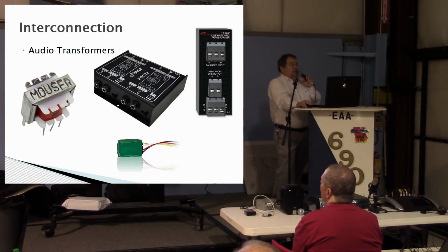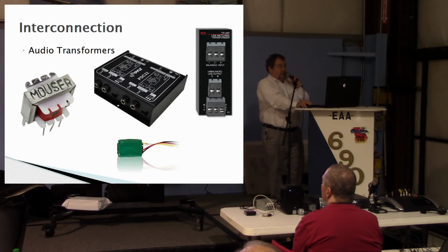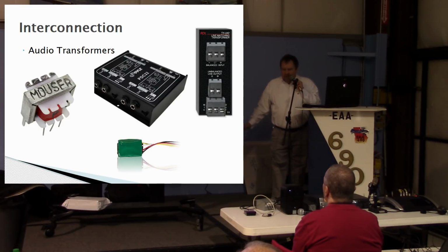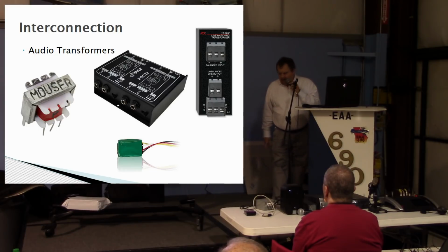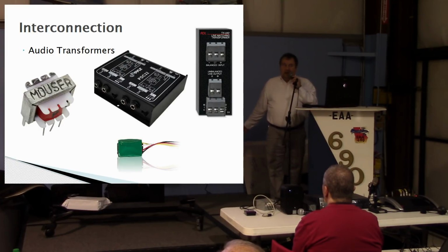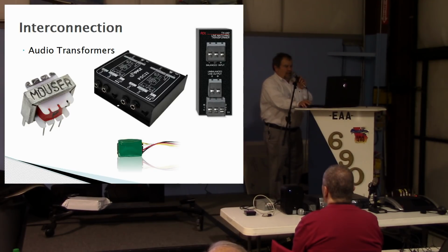You can buy a little box like this. This is called a direct box. This is used by the recording industry. You'll see them on stage with varying equipment. This is particularly important when you've got the mixing boards in the back of the room and a mile of cable run up here, and then all your instruments plugged up here. They're plugged into different AC jacks for sure, and there's going to be a buzz, guaranteed. So you always use this direct box.